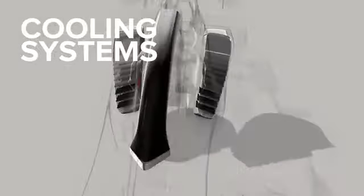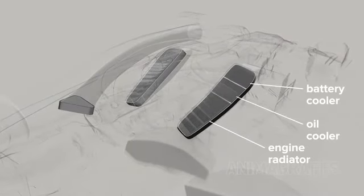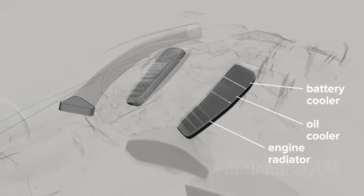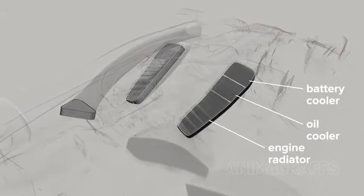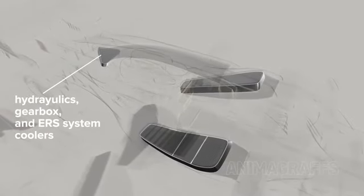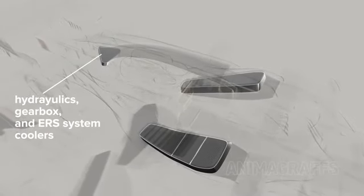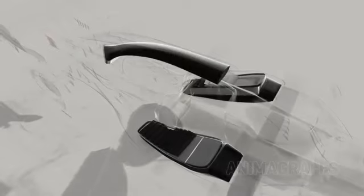Cooling. Various additional radiators for cooling occupy the opposing side pod. This includes the main engine cooling radiator, an oil cooler, and a battery cooler. An additional bank of radiators sits in the path of a separate roll hoop air duct to cool hydraulic oil, gearbox oil, and the MGU H and K systems.